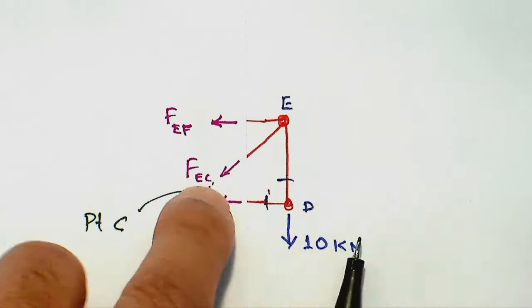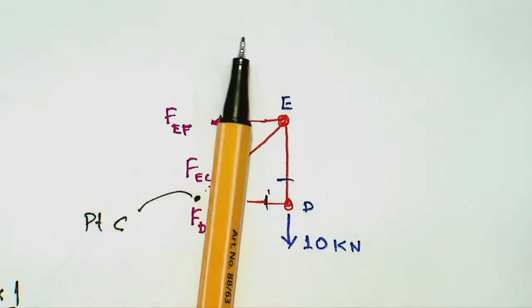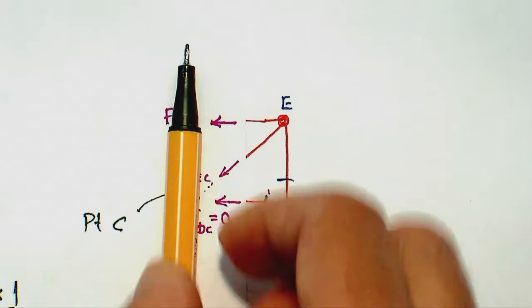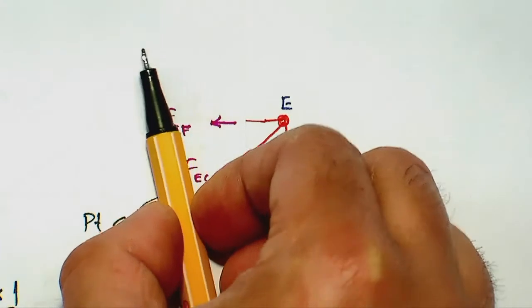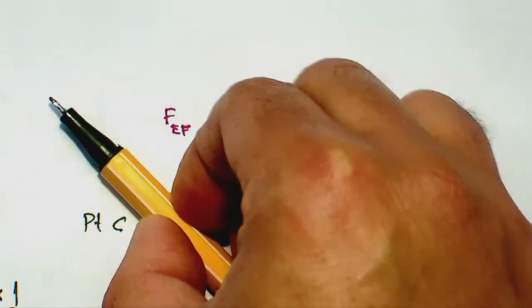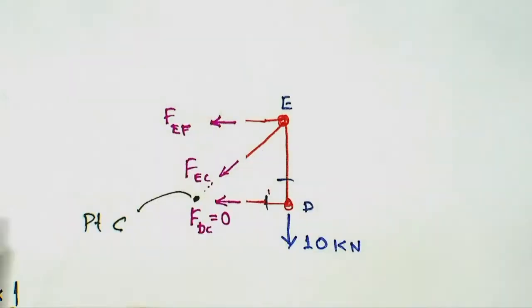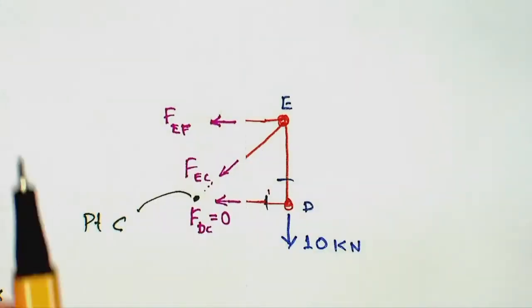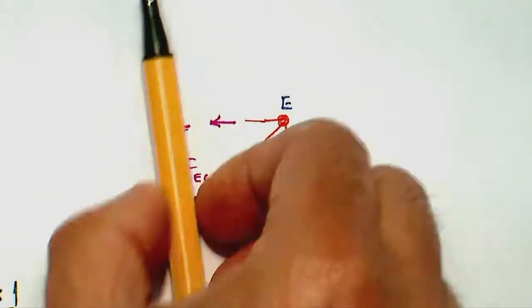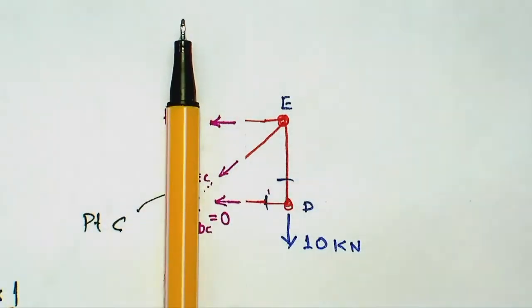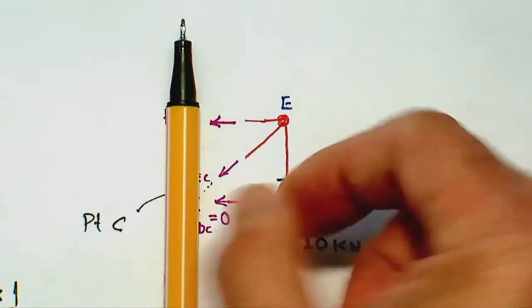And then you have to see what sort of direction that moment is. Now that force about point C will rotate my pencil in the counterclockwise direction. So always put a lever or a hinge or a rotation point about which you are taking moment, and then imagine the force is trying to rotate your pencil about that point.